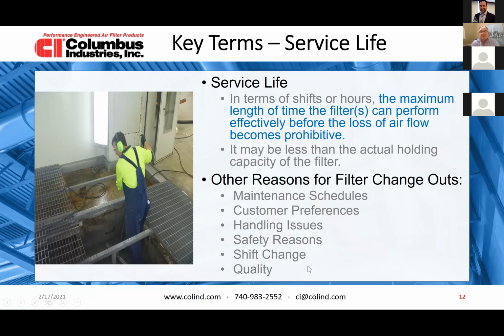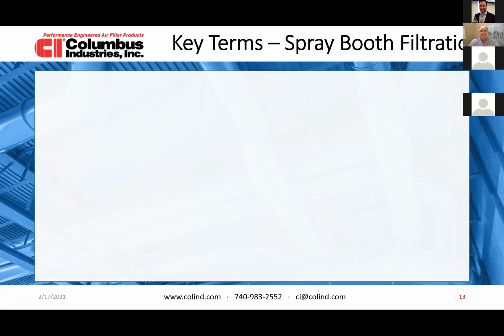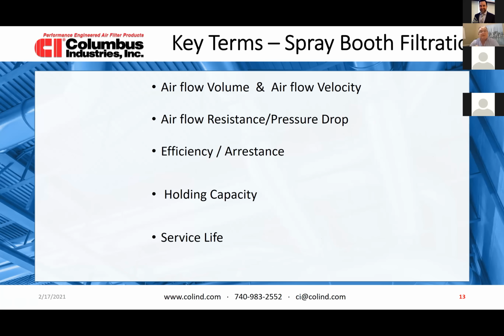And anytime you have a booth that is not balanced, anytime you have a booth that has too much resistance, it does immediately affect your quality because the air will create some turbulence within the booth. And then your overspray is not just hitting the filters, it could be going around and hitting the parts that you just painted. So these key terms, we summarize them.